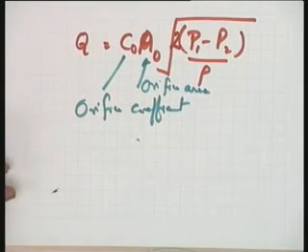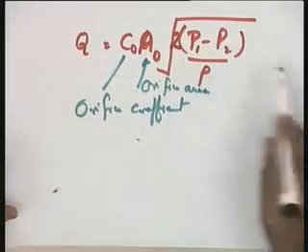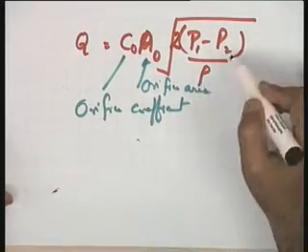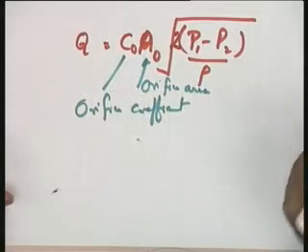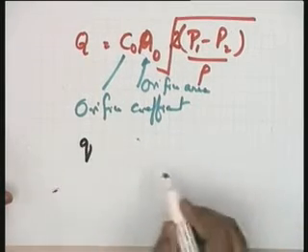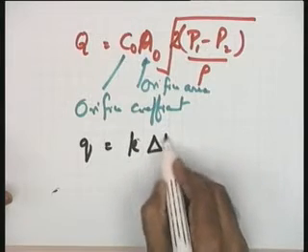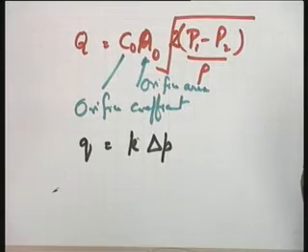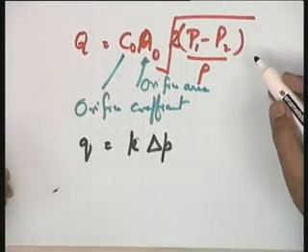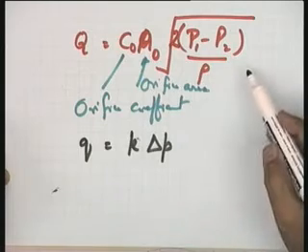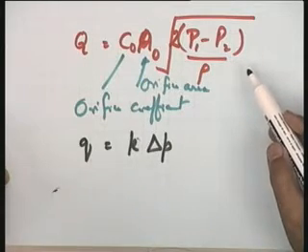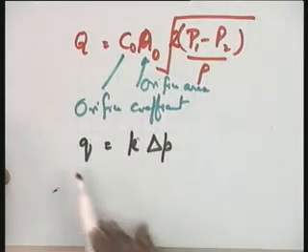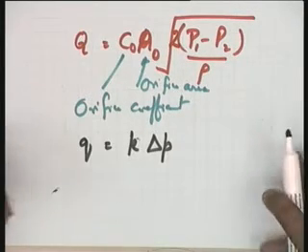Now, you see that this is a highly nonlinear relationship between Q and pressure. So, if all these numerical values are given, you can linearize this using Taylor series expansion about the operating point and hence get a mathematical model Q equal to K into del P. I leave it to the type of data available to us, whether the manufacturer's data is available in terms of an experimental curve or in terms of this type of nonlinear relationship. The point is that by linearizing this, or by taking the slope of that particular curve, we are able to write the equation Q equal to K into del P.